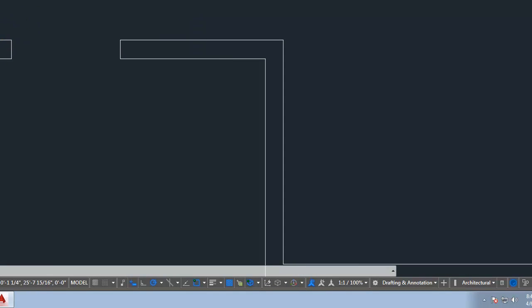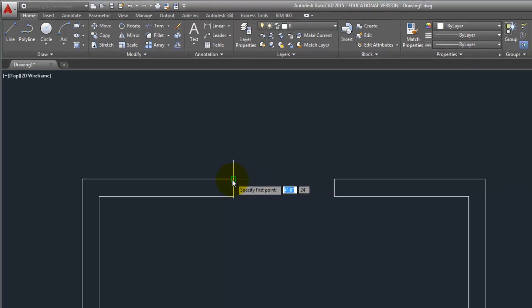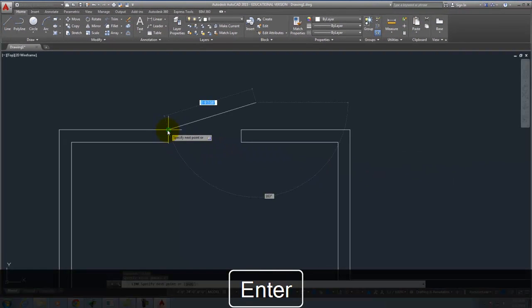Now we're going to continue drawing with more of these shapes. Right? It says it's under the modify ribbon. I don't know. We're going to continue drawing with a few more shapes. So for example, I might want to put a window in. And so we'll flip this over so I can see where this window would be. I have it 1 foot from the door. So I want to go over 1 foot. So I'll type 1 foot.